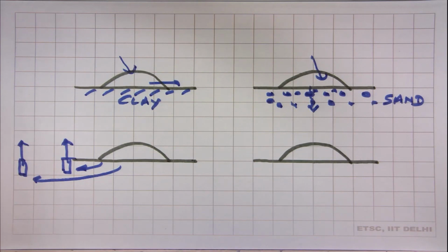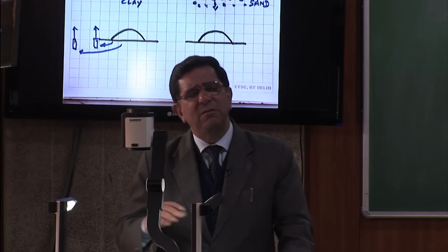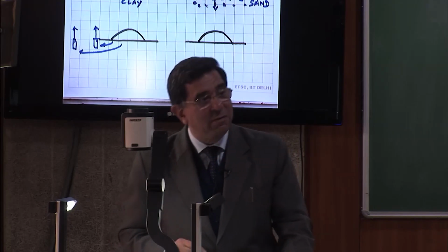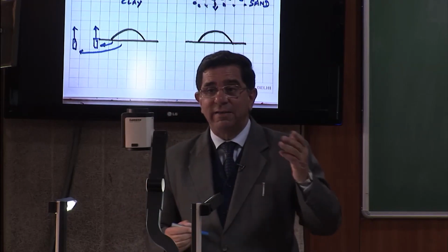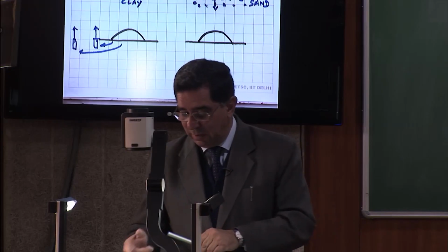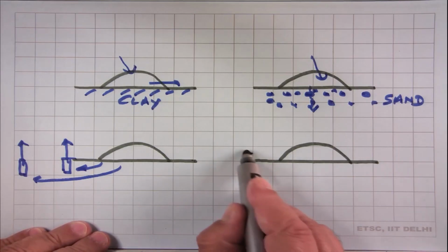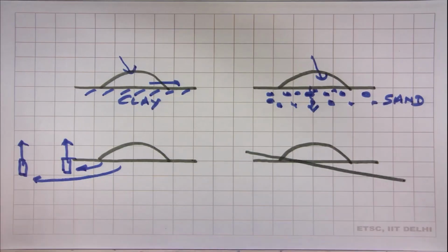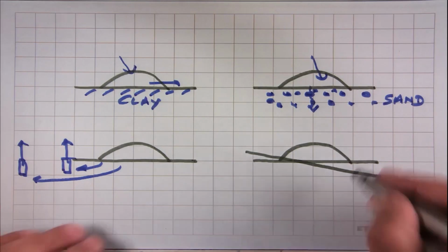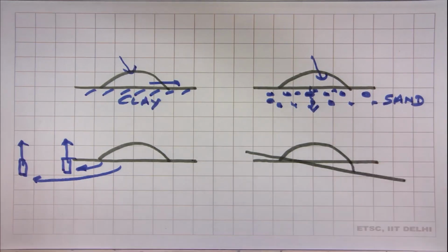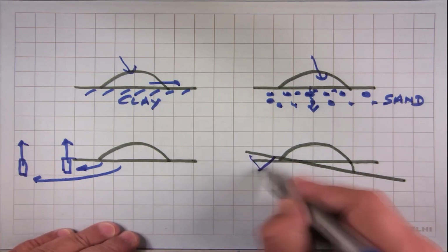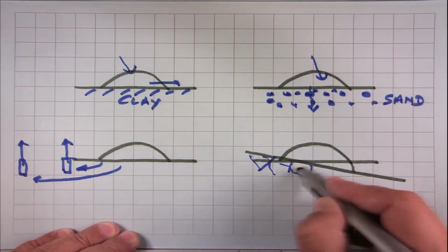If you have rock on the surface, it can also be inclined. Hill slope, gentle slope. So the moment you have an inclined slope, your hydraulic gradient is up. So instead of the ground being like this, you have, let us say, a ground like this. And let's say this is your waste dump. Same quantity, but now the rock has got fissures, cracks.